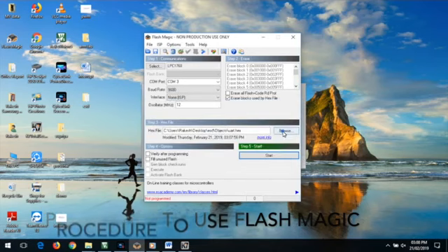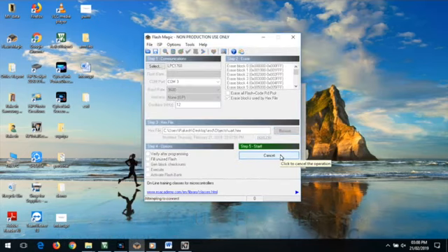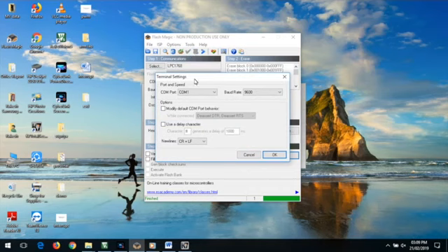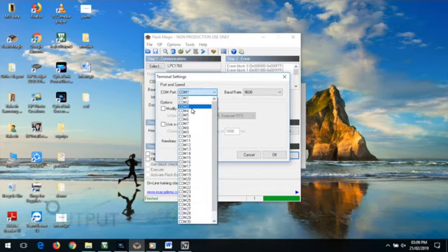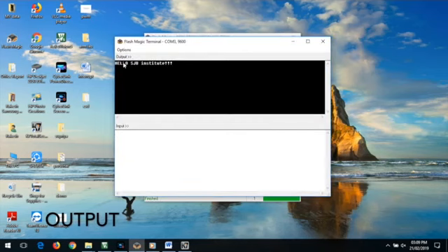So now start downloading the file. You can see that green bar. In UART, you will always see the output in the terminal, which is the port COM3 at 9600. Click on OK. You can see the message here, "hello SJB Institute". This is how the UART transmission takes place.